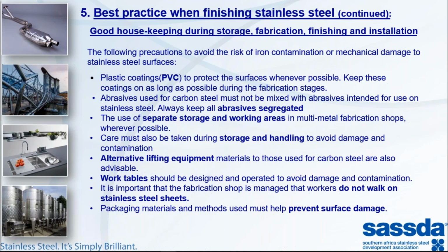Try and get your tubular deliveries, your square tubing, your pipes and so on, in plastic sleeves. Please do not, and it's such a simple thing, but we still see it quite often, mix your abrasives. Keep them segregated. Do not use abrasives that were used on mild steel.